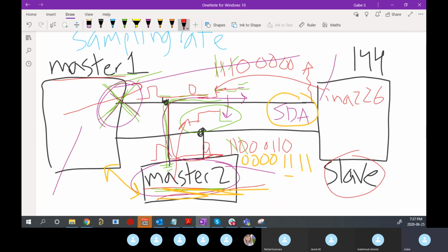I don't know. Sabrina? You run the risk of potentially shorting your pin because of this. No. Good question. Why no? Because we're not push pulling, right? None of the masters are driving the pin to 1.